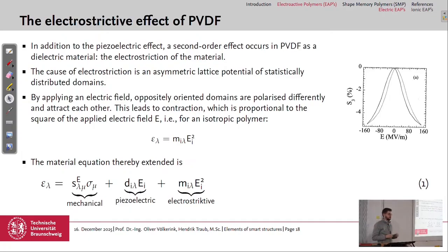So if you would cure it at room temperature, you have lower performance, and also the Tg of the material, so the glass transition temperature, rises with higher cure temperature. So you can use it also in a higher temperature range then. So it was a requirement from the CFRP material. But there are epoxy materials which could cure at room temperature, you're right.